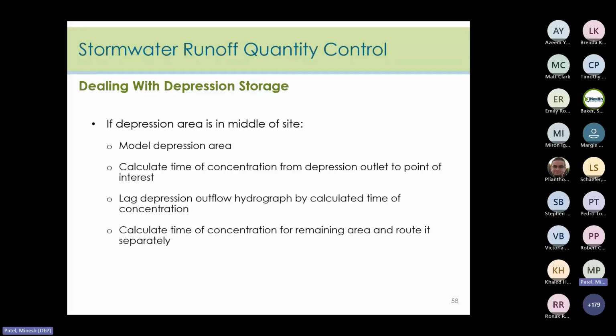And lastly, you will need to route the other sub-drainage areas that do not go through the depression directly to the point of analysis. So a combined hydrograph, with the correct timing and peak flow, will be the result.